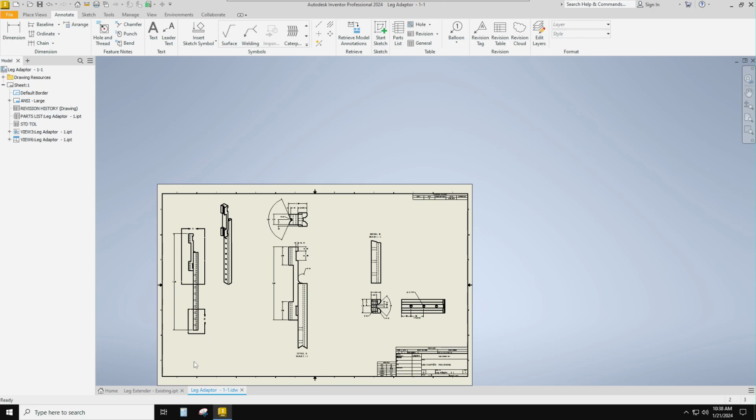I happen to use a D size drawing. I like large drawings that let me get my parts drawn big. But here's what goes on a drawing: the information, and only the information, that's required to build the product. And it should be done in the most general way possible, in other words, the fewest number of views. Now, it doesn't maybe look like it from here, but remember, it has to be crystal clear.